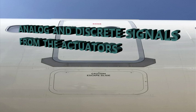Now you have a local servo loop, and that is done on each actuator, and it's done with the modules, whether it's your FCRM, your flight control remote module, or your other one, your electronic module. Those are controlling the valves on the actuators so that it can get the right deflection. Remember I said how important it is to have the right deflection rate as well as the angles. This is the information that the computers are getting, so that they can give those commands and control those valves.